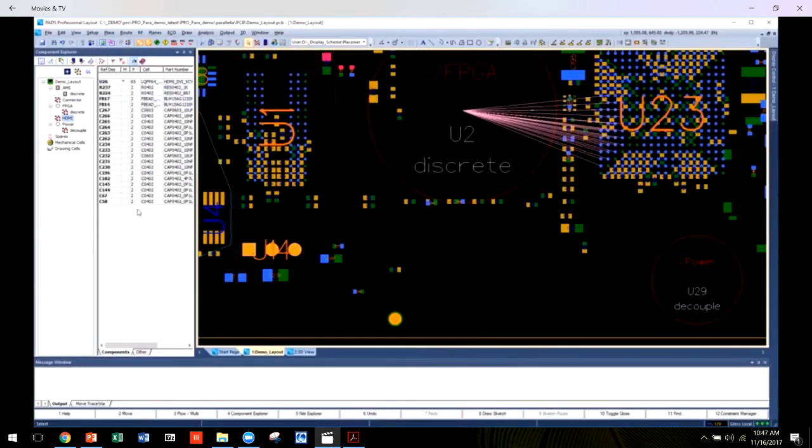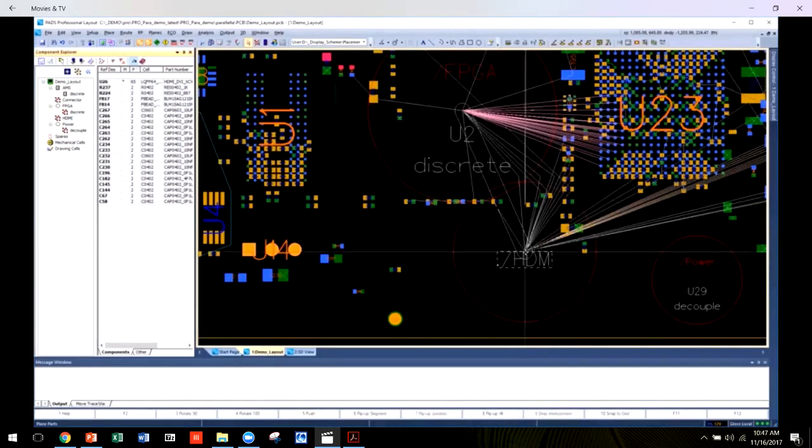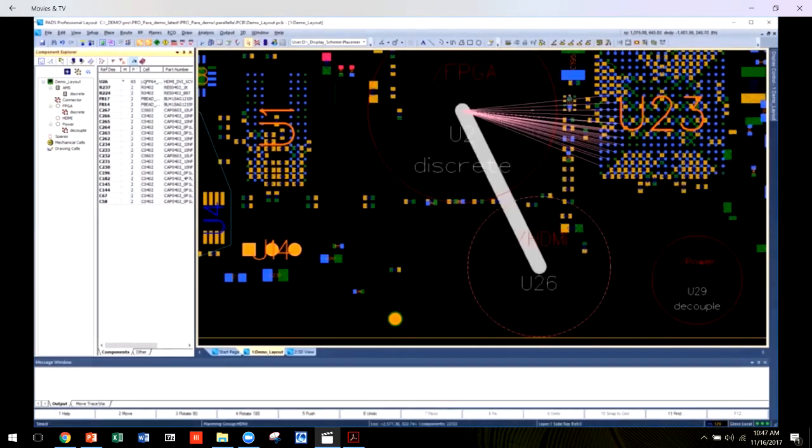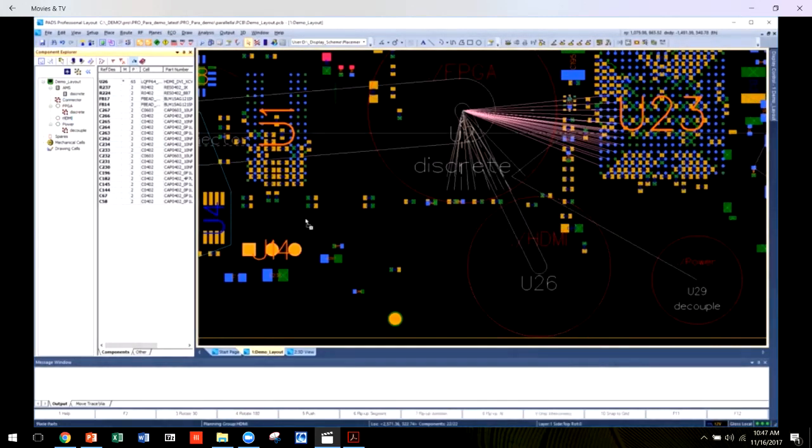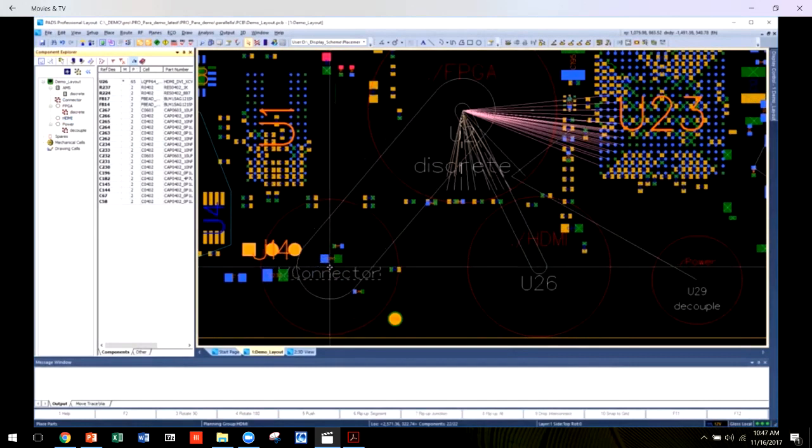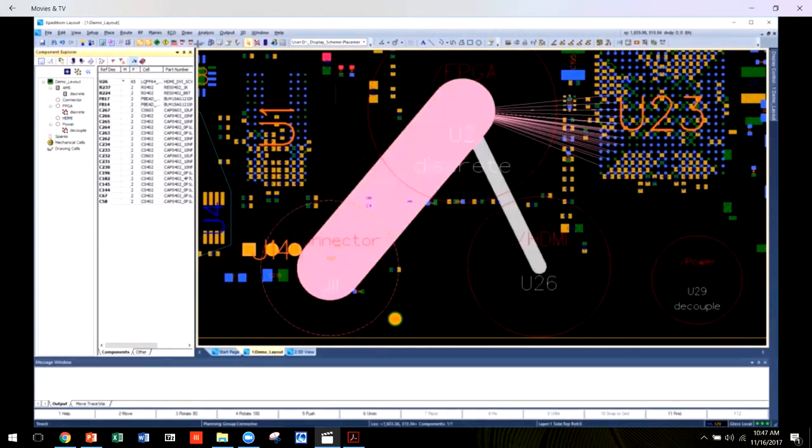However, why not take advantage of the planning groups of relational components? You can still place the components one by one, or use the Arrange dialog to place the group of components in a spiral-like fashion. Placing by group allows for optimizing floor planning. Connectivity relationships are shown between planning groups to easily visualize the connectivity flow through the design.